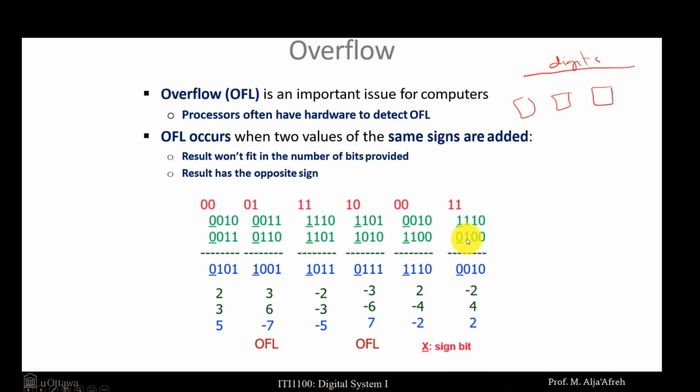So basically here, if we add, this is what, guys? As you can see, that is -2 added to 4, because this is in 2's complement. Remember that it is in 2's complement. -2 plus 4, the answer will be 2, and we will not have an overflow.